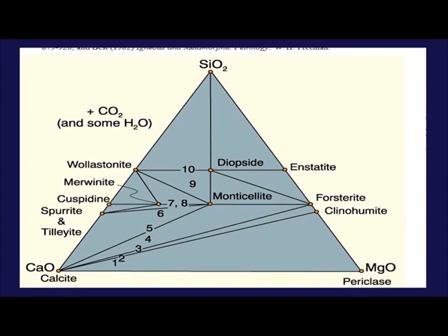In order to understand projection in multiple dimensions, it is easiest to begin with a simple example that we can see easily. We can simplify the diagram from a ternary one to a pseudo-binary MgSi diagram, in which diopside is projected to a point at 33% Mg to Si 66%, as illustrated in figure. By performing the projection, we have managed to reduce the ternary system to a pseudo-binary one.